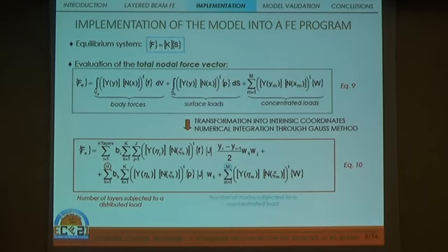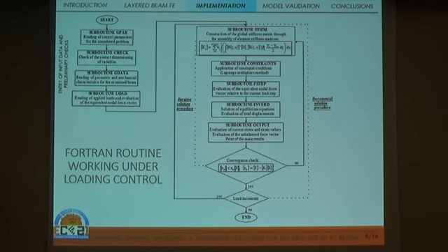The nodal force vector is constructed by following the same procedure as before, and it is updated at each loading increment, since the equilibrium system is solved by means of an iterative incremental procedure due to the nonlinearity of the material. And this is the structure of the program.